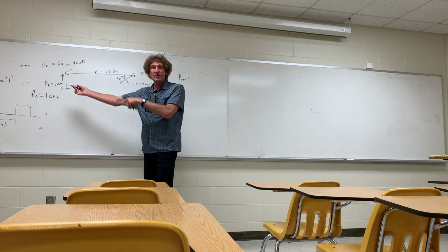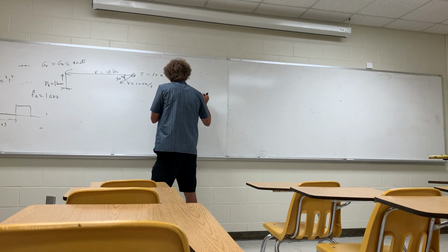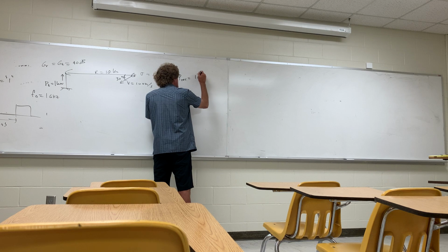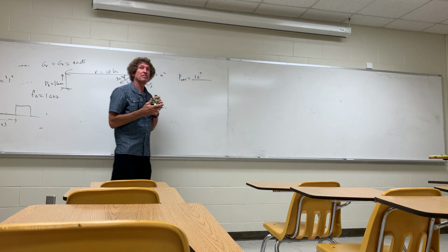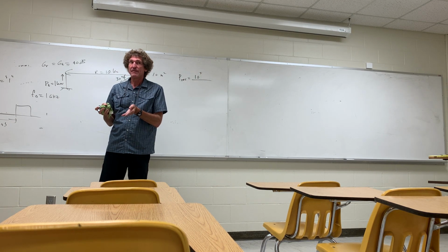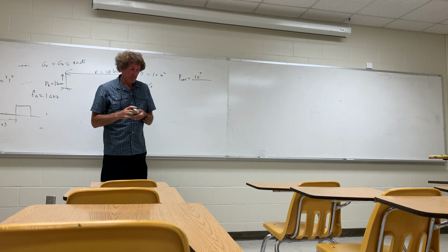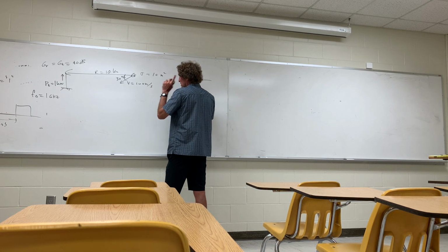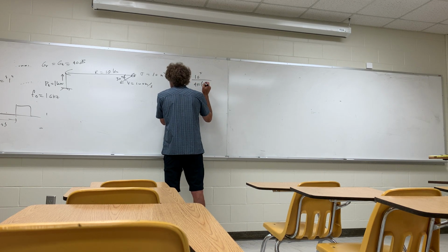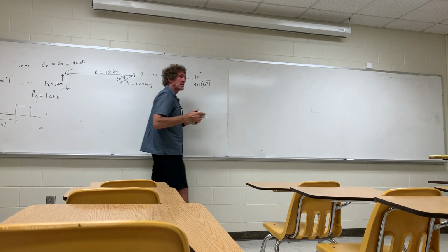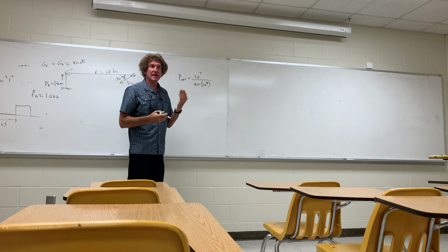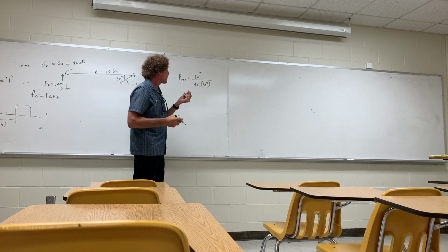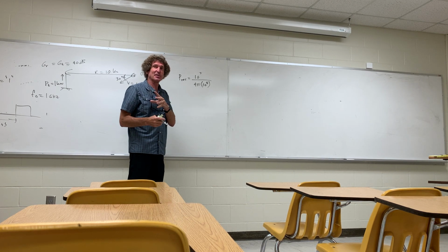Well, you always start with the transmit power, right? Start with 1 kW, or 1,000, or 10 to the third. What do I do from there? Divide by 4 pi r squared. So divide by 4 pi r squared, and r is 10 kilometers. So 10 to the 4 squared would be 10 to the 8th, right? Y'all agree with that? Now that's the power density, not quite the power density on target. What do I do next? Sorry. Multiply by gain. Right.